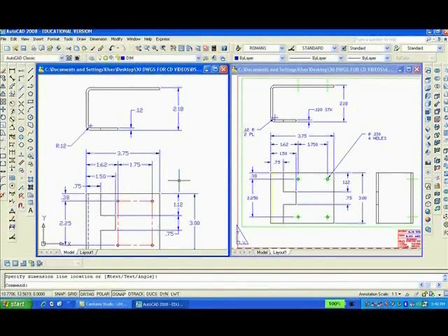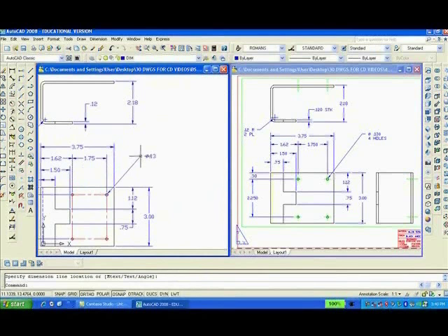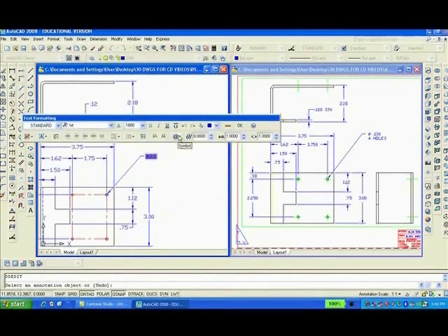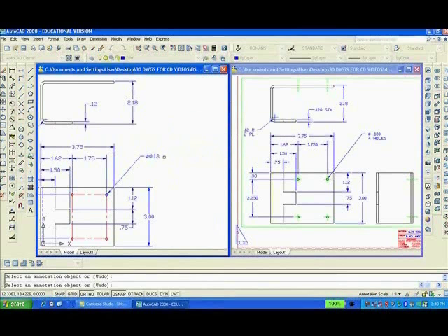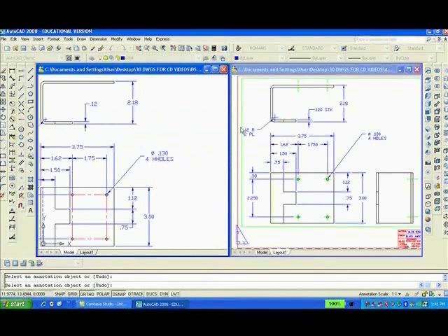And we'll have to call out the holes. So I'll pan, move over like that, and we'll give the diameter of that hole. Remembering that we can edit it. We can put a diameter symbol in front of it. That was weird. Try it again. Why don't I just delete the whole thing and start over? I can type diameter space 0.130, enter 4 HOLES, or just 4x, it doesn't really matter. I did it again.